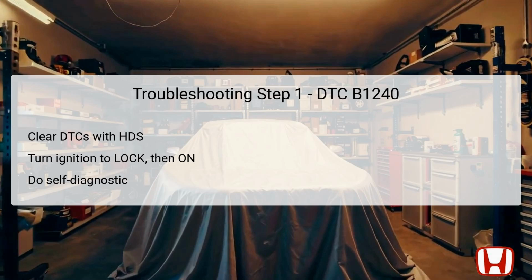Following this, engage in a self-diagnostic process using either the HDS or the vehicle's climate control unit. Finally, check for any DTCs again to see if DTC B1240 is indicated. If it appears, proceed to the next step. If it does not, this might suggest an intermittent connection issue, warranting a closer inspection of the mode control motor circuit for loose wires or poor connections.